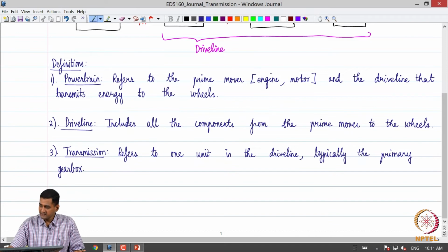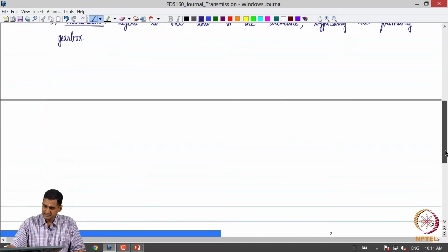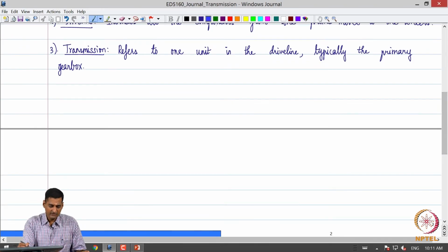But before we look at transmissions, let us first reason out what are all the expectations from an automotive powertrain. Then we will be able to better understand what the current powertrain provides and why the transmission is realized the way it is currently. If you look at most vehicles today that are powered by IC engines, we will have a multi-speed gearbox which the driver controls to get the output from the powertrain. What is the reason for that, and how does one choose those gears?